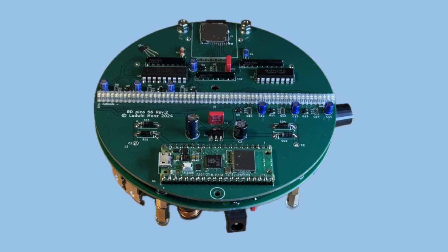The electronics were developed with wired components so that the boards can be assembled by hand. The MOSFETs can be either classic wired components or SMD components. The SMD components are considerably cheaper, but more difficult to solder. The same applies to the SD card reader. This can also be installed as an SMD component and alternatively as an SD to micro SD adapter. It is glued on top of the circuit board and the contacts are soldered by hand.